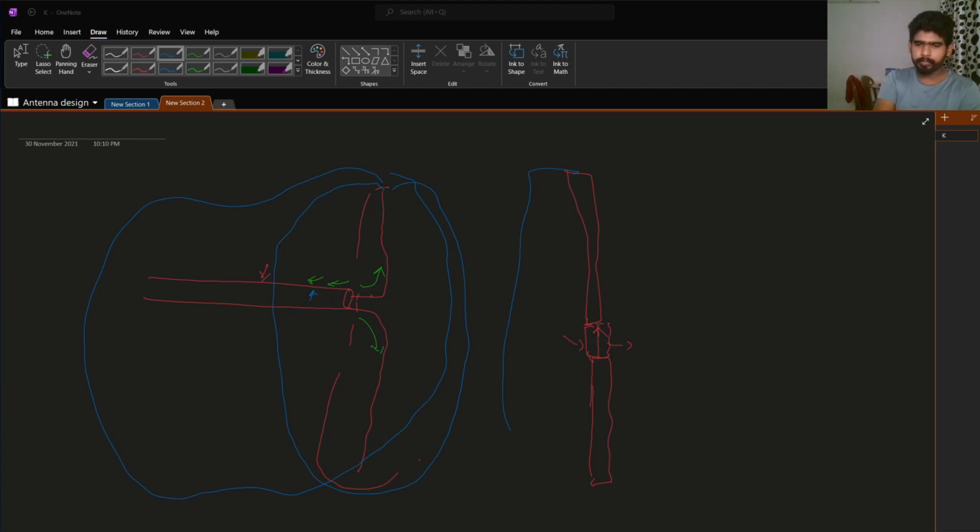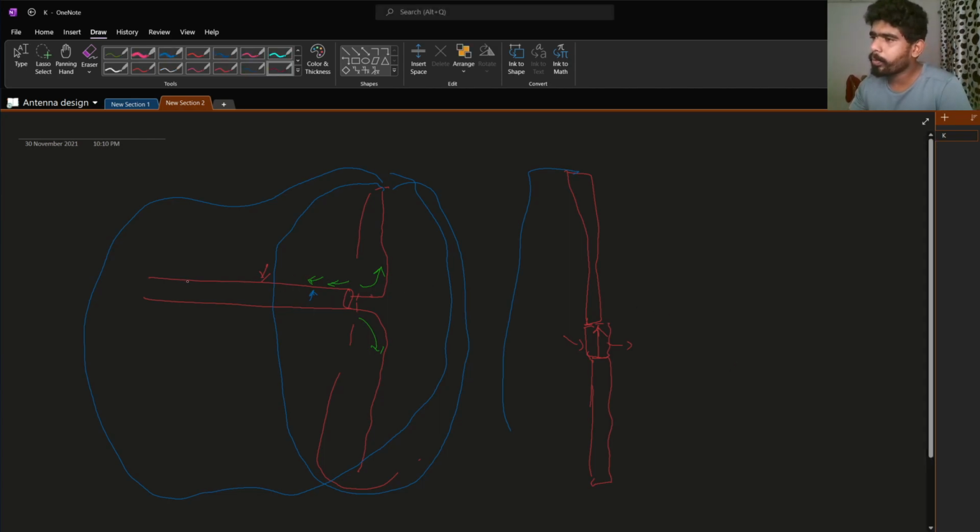So the best option to get the actual performance of the dipole is to put the same coaxial cable here in the simulation. So in the simulation you model the coaxial cable. You almost don't need to model a lengthy cable, but if you're planning to model a cable of approximately this distance, then you have to model the cable here also. Then you feed this antenna, and only here do you need to excite. And I prefer to use a wave port and close the wave port by placing some metallic sheet here.